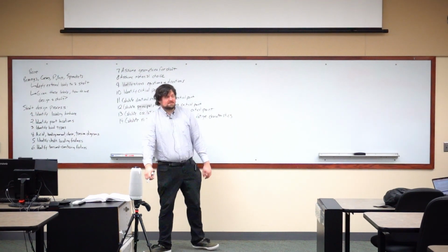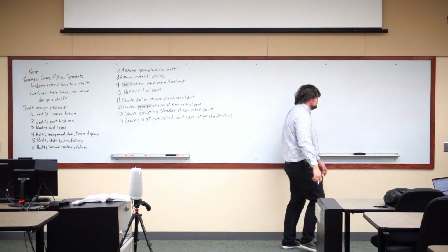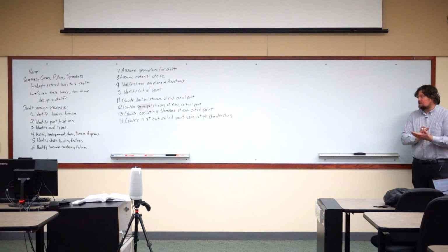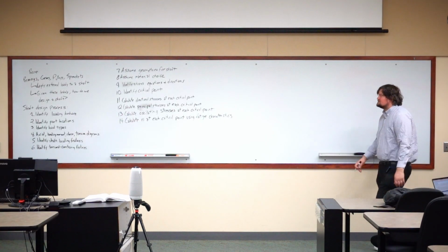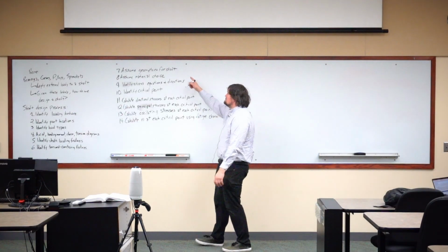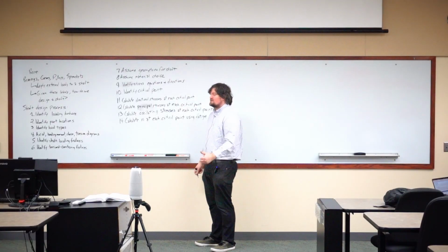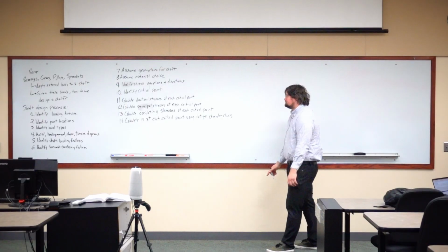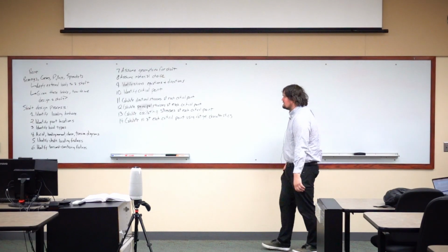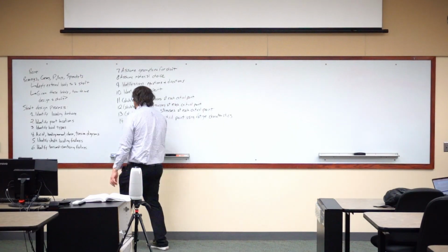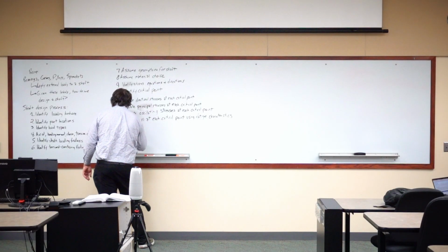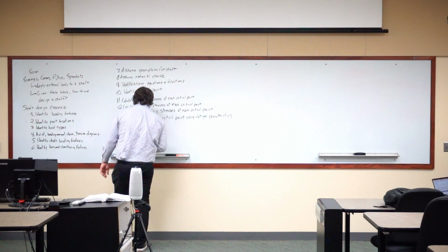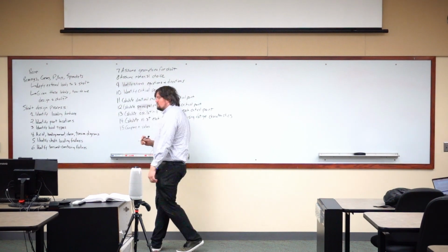Okay, so now that we got to step 14, a lot of these are steps that we've already done, and some of these are just simply going to be like, hey, let's assume the shaft is a solid 1-inch shaft diameter. Nice. But once we get here, our last step is to compare every one of your n values.